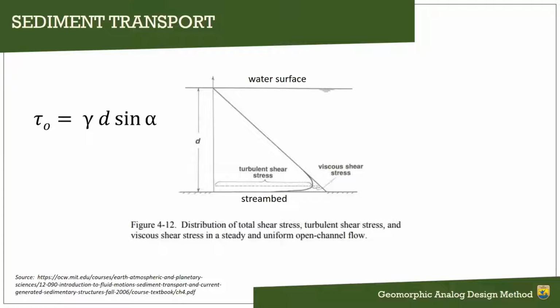Put another way, the shear stress, which is the force exerted on the channel bottom, is higher at deeper flows. This is because the weight of the water is more at deeper flows. You might have learned this from wading a stream. You want to always look for the shallowest part of the channel to make it easy to cross. You wouldn't go crossing in a narrow, deep section.